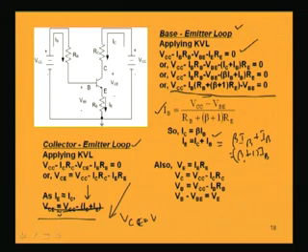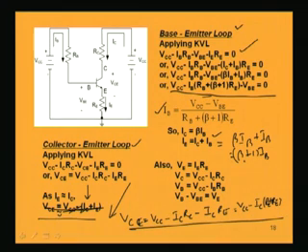So VCE equal to VCC minus IC RC minus IC RE, which is equal to VCC minus IC into (RC plus RE). This is the expression, VCC minus IC into (RC plus RE). That means I am taking this IE to be equal to IC. With this approximation, I get a simpler expression, but the exact equation is the earlier one; only a simplification a step further gives you this equation.